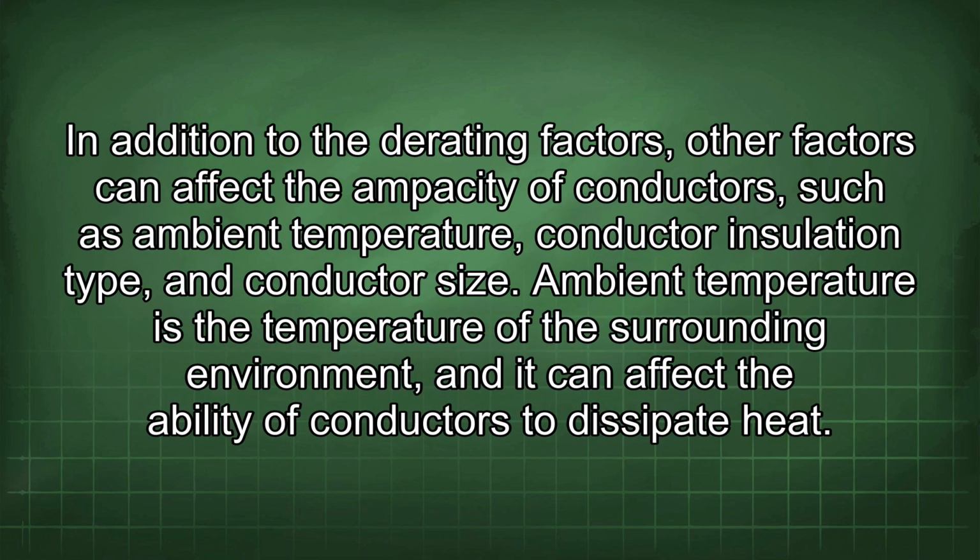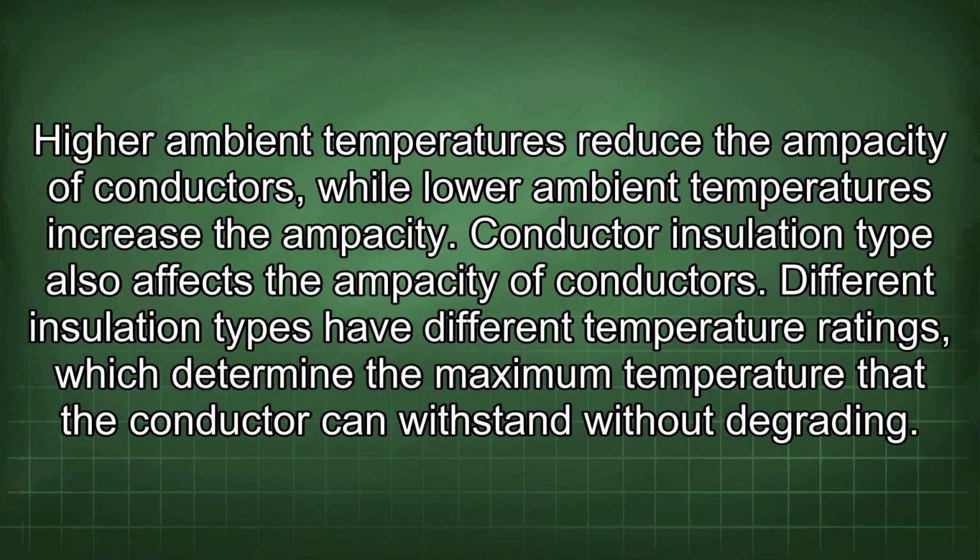In addition to the derating factors, other factors can affect the ampacity of conductors, such as ambient temperature, conductor insulation type, and conductor size. Ambient temperature is the temperature of the surrounding environment, and it can affect the ability of conductors to dissipate heat. Higher ambient temperatures reduce the ampacity of conductors, while lower ambient temperatures increase the ampacity.